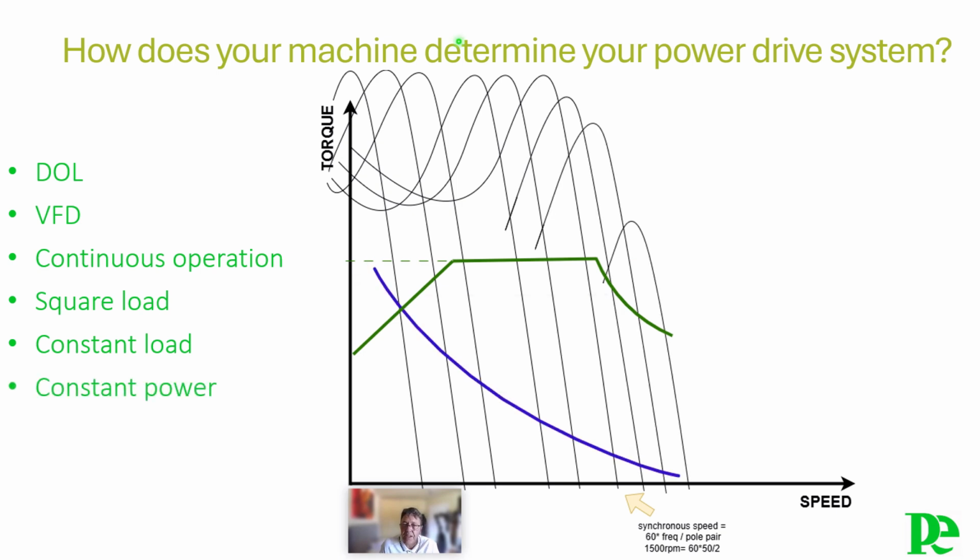Above the base speed, we now go into the zone called constant power. Above the base speed, that is this part here, the continuous available torque decreases, of course, as it is constant power, inversely with the speed. Notice also that there is a substantial decrease in available transient torque in the oversynchronous zone. Examples include center winders and grinders.